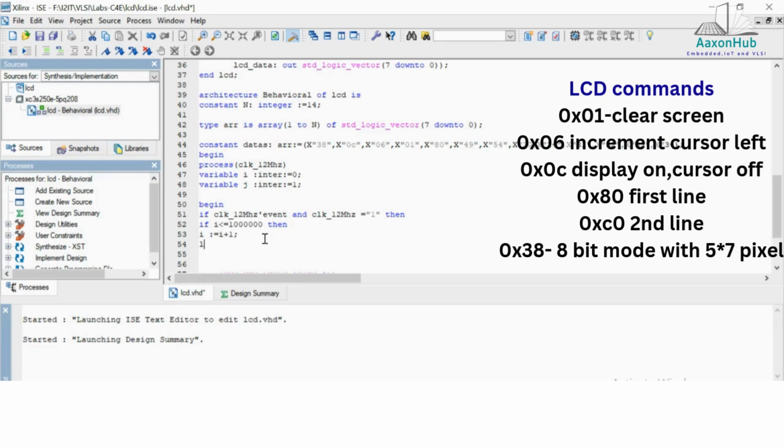After that, you need to initialize the control signal for the first data. So you will activate this as by your enable signal. So you need to assign enable signal as a 1. So whenever you wanted to give the data, the condition for the data is RS must be, if at all it is command, then RS must be 0, RW must be 0, and enable must be 1. So here in our case, RW is grounded, so we are not considering RW, but instead of that, we are taking enable signal. Clear? So in that manner, you simply take out this enable signal as a 1